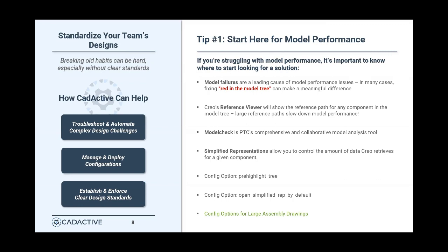So if you have an empty rep, then you can open an entire, let's say it's a satellite or something, some massive model, instantly. And then we can be a lot more explicit about what we need to work on, what we need to bring into session, right? So we can control what we're loading in order to improve our time and not have to sit there waiting on Creo forever. So that's a user-defined rep.